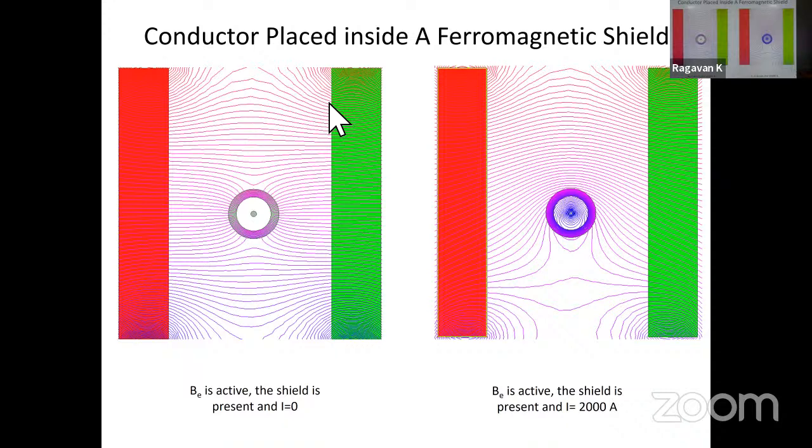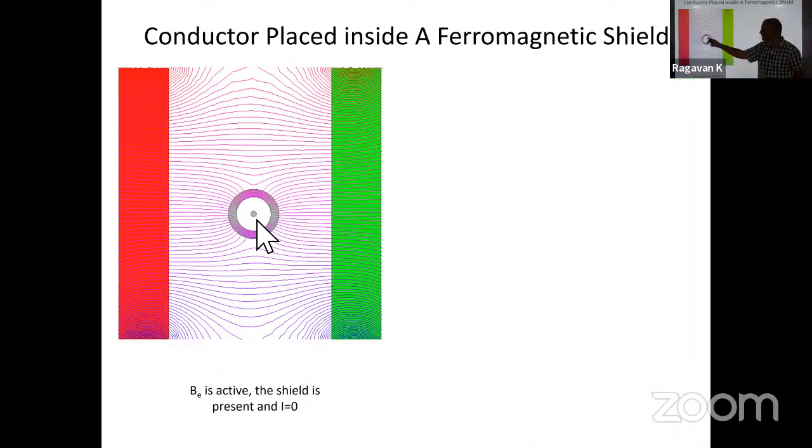If you apply Maxwell's stress tensor, you know that the external field is not coming inside. If you apply Maxwell's stress tensor somewhere here, don't go out. Use that contour within the shell, inside, but around the conductor. The external field is not coming inside. Based on that concept, the self field cannot put any force on the conductor, right? The conductor field itself cannot drive it in any direction. So that is how we say the force on the conductor is 0 using MST or Lorentz force. For energy, you can say that if there is no field, whether you move the conductor a little bit up or down, there is no change in energy.